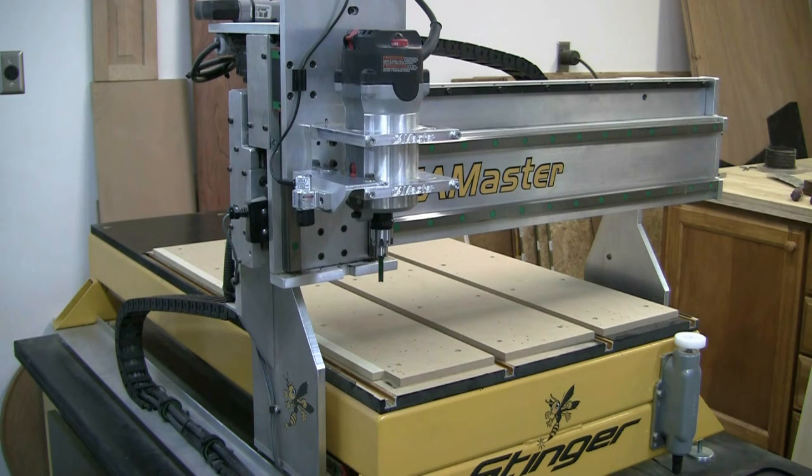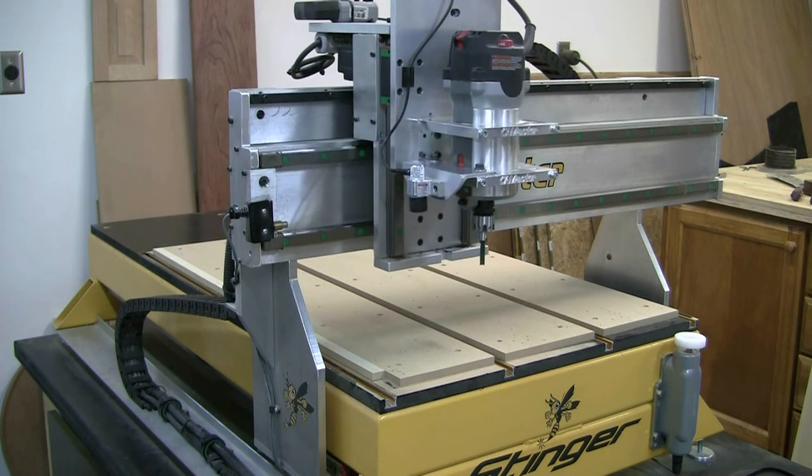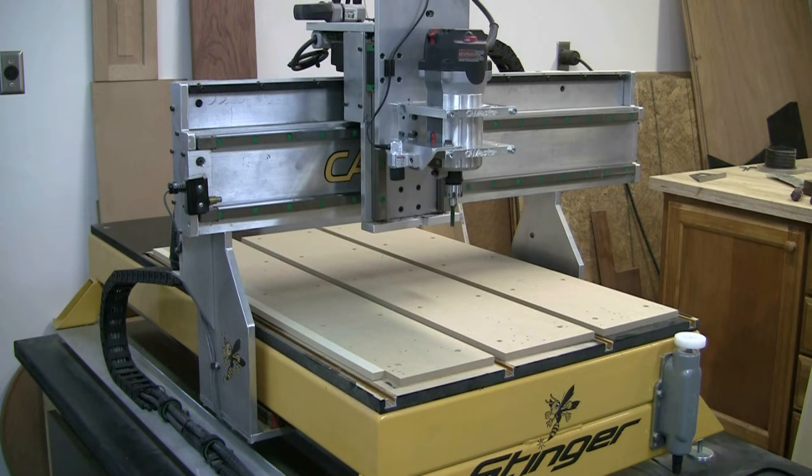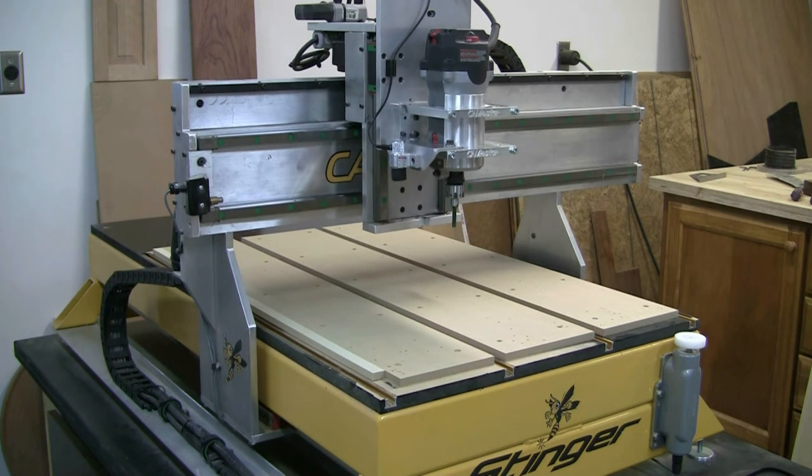If you have any other machines, you might want to read your manual or something like that. The only thing that you've got to be careful of now is I am still below my spoiler board. So to really fix that, since I lowered it 0.4, I go to my screen and I type in Z.4, and that will actually take me to the spoiler board. That will actually jog me down.